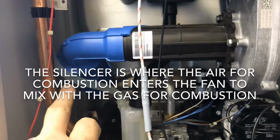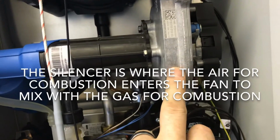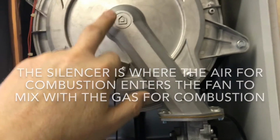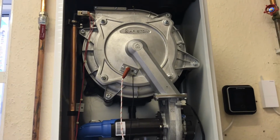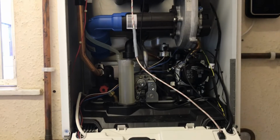This is a silencer to make it quiet. The fan sucks air and gas together, mixes it in this tube and sends it into the burner, which burns 360 degrees. This is Ariston's new burner. Okay, so that's what the inside of a combi boiler looks like today.